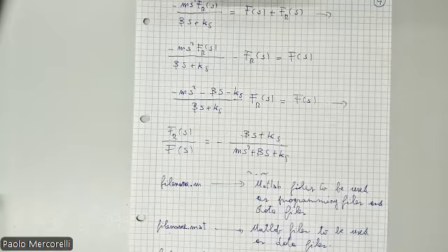I hope to go more in depth with linearization, because we also work with linearized systems in my lab. This is also a topic of control and automation, where we work in s. But to work in s, if the system is not linear, this is not possible. Please pay attention: these results are valid just if the system is linear.